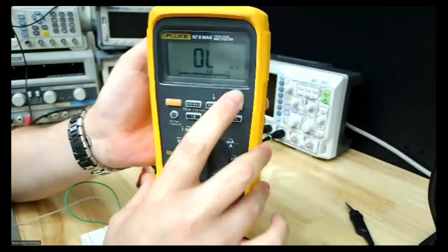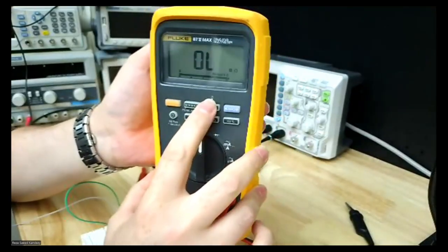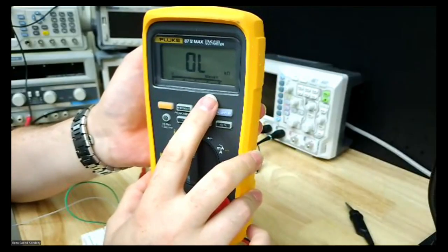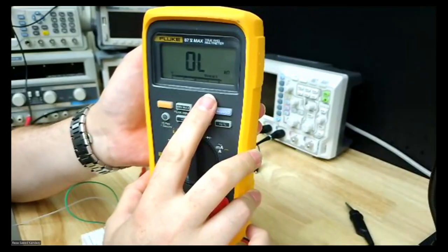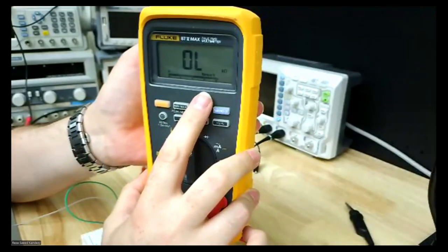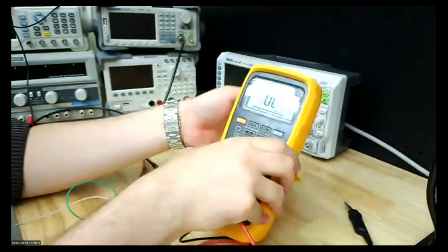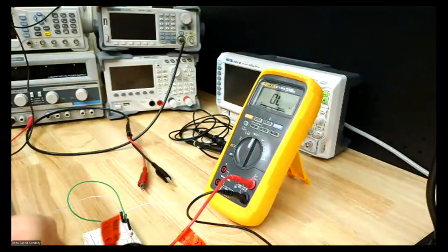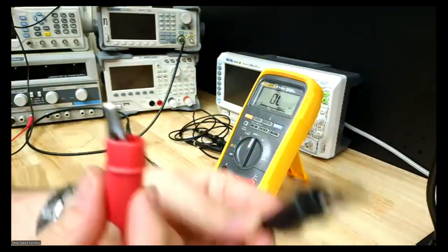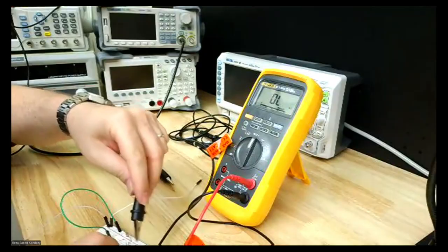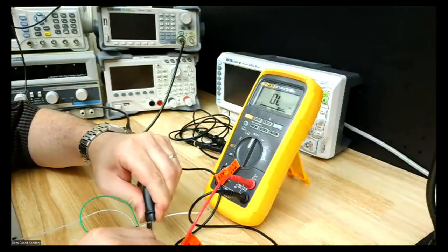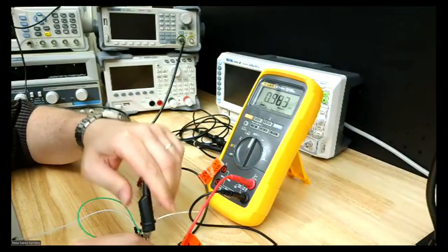You can see here there is a range. I'm gonna change the range to the kilo ohm. Are we good? Because I'm expecting a kilo ohm range value. Now, I'm going to put it down and connect the two probes across my resistance. So one here, another one here.